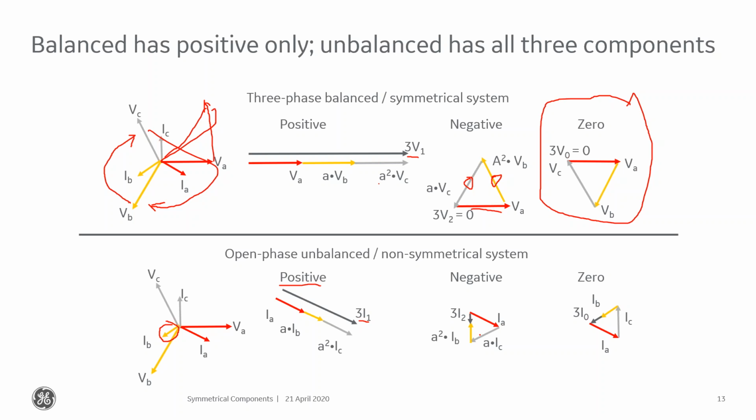Okay, now do I have negative sequence quantities? Well, if I take my A phase here, and then I take my shifted C and put it here, right? And then my shifted B and put it here. Well, now, yes, there is a small amount of negative sequence current right there. So negative sequence current would actually be 1/3 of that. So there is some negative sequence current.